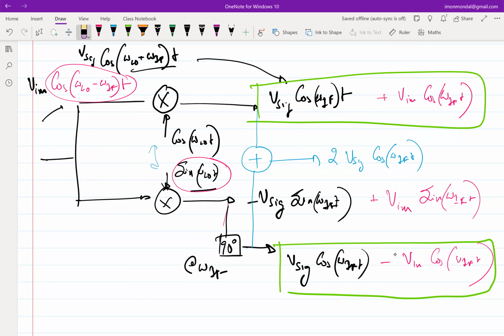When I say requirement, what I mean is that the further down the signal chain you carry your image, which means you are carrying extra unwanted stuff into your signal chain to be cancelled somewhere else, you're carrying the burden and assuming that you're going to cancel it later on. If you can, you cancel it upfront only. Then you don't carry the burden along with you.